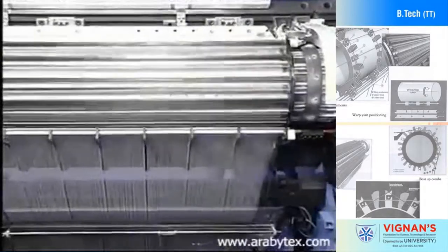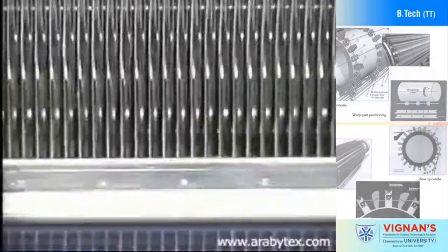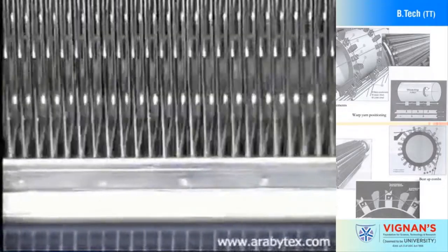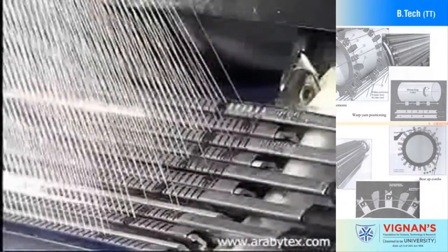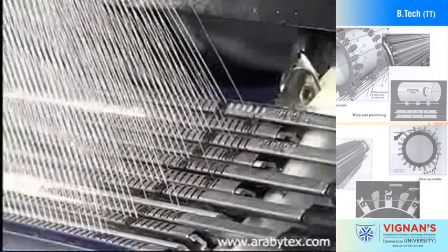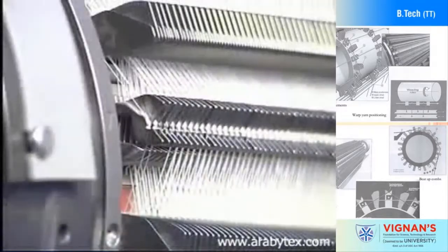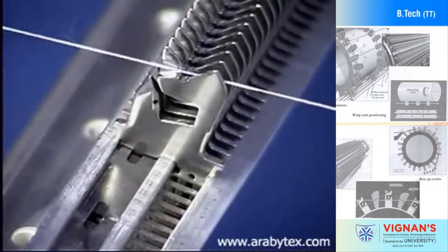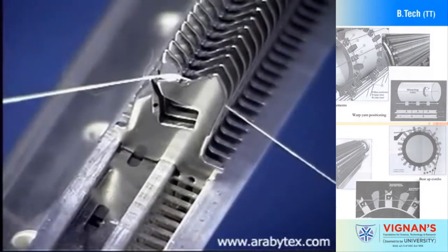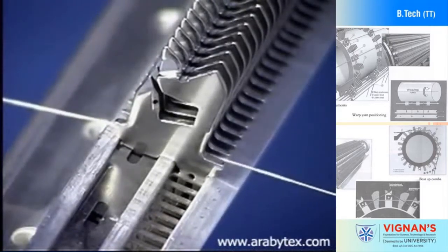The shedding motion begins with the warp ends being aligned properly with the shedding elements on the weft channel. The shed formation unit and warp positioners move the warp ends from side to side to position the ends properly with each shedding element. The ends may be positioned on top of the shedding element or to the side of the shedding element. Ends placed on top of the shedding elements create the upper shed. Ends placed to the side of the shedding elements form the lower shed.